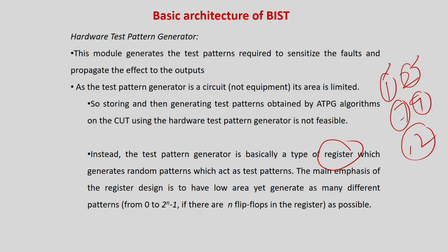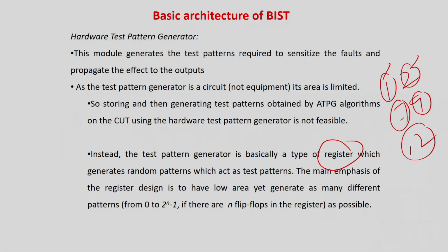As we'll show you, there is something called linear feedback shift register based pattern generators, where if you randomize this order, the size of this combinational circuit becomes very, very small. So the main emphasis of the register design has to be low area, yet generate as many possible patterns in the flip-flops.